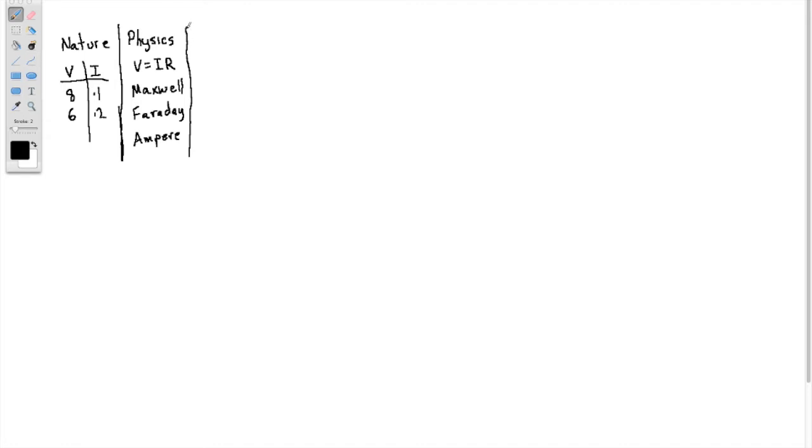Okay, so here's a new abstraction, and we don't necessarily just want to use the laws of physics. For example, if we have a light bulb and we connect a certain voltage, we don't want to have to calculate the current and the electromagnetic field, in and out of the light bulb using Maxwell's equations. And so this next abstraction, I'll just write LCA here, and I call this the lumped circuit abstraction.